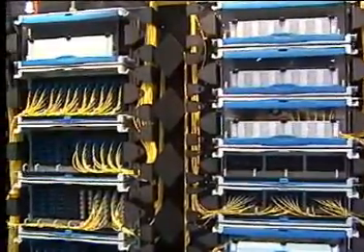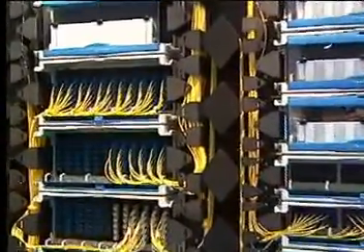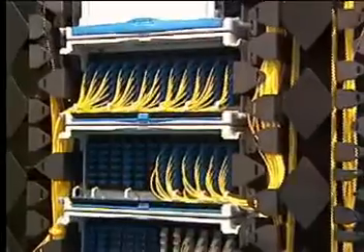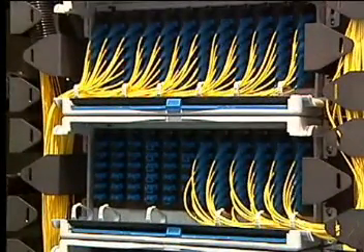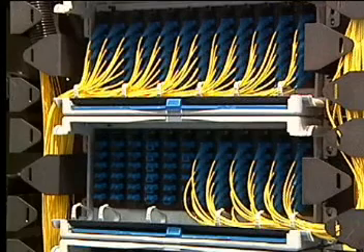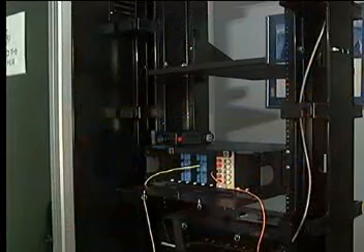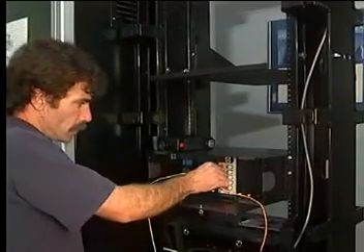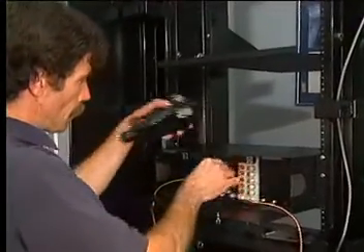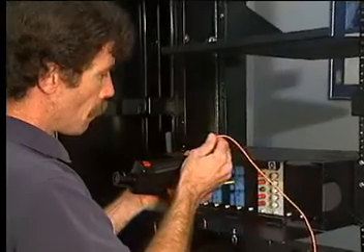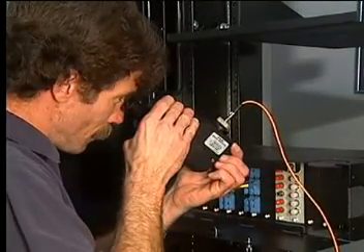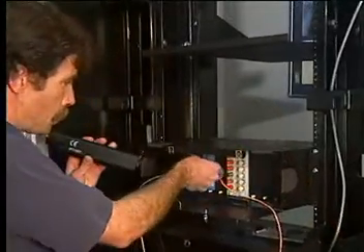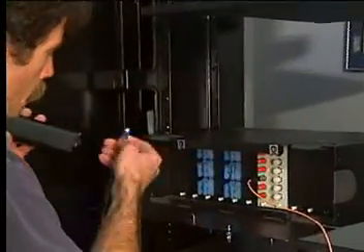It is important to be able to verify the condition of connectors used in fiber systems. How clean are they? Are they scratched or damaged in any way? Being able to answer these questions is key to keeping high-speed fiber networks operating efficiently. A number of inspection scopes are available to examine connectors. Handheld microscopes allow the technician to closely view the connector ferrule. Scopes are most commonly available with 200 or 400 power magnifications.